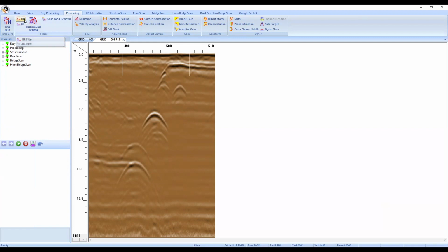Remember, IIR and FIR are the two places where we can apply constraints to what the receiver receives. This is what the high pass and low pass filter does. We basically put a fence around the receiver and say, we only want you to see things in this specific frequency range, and everything outside of that range, I want to filter out and remove. You have two options to do this, FIR and IIR, and I would strongly suggest using the IIR filter 100% of the time for this.